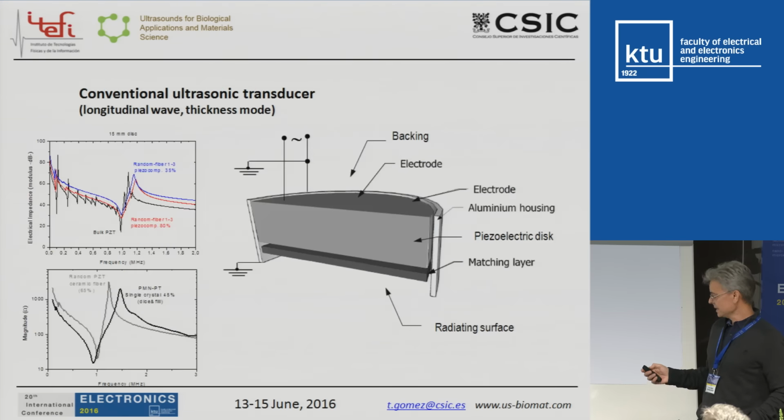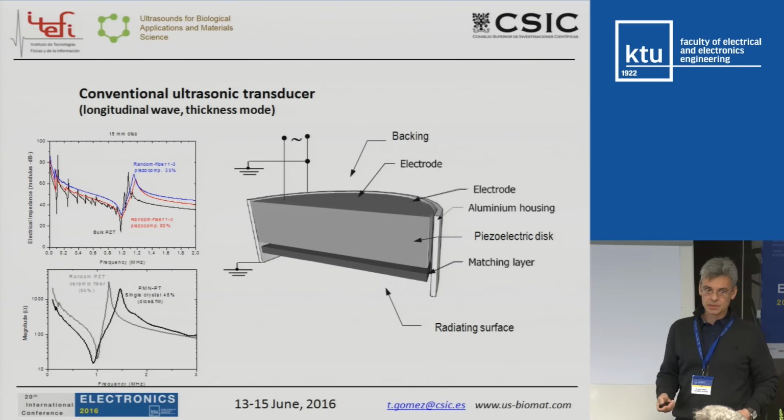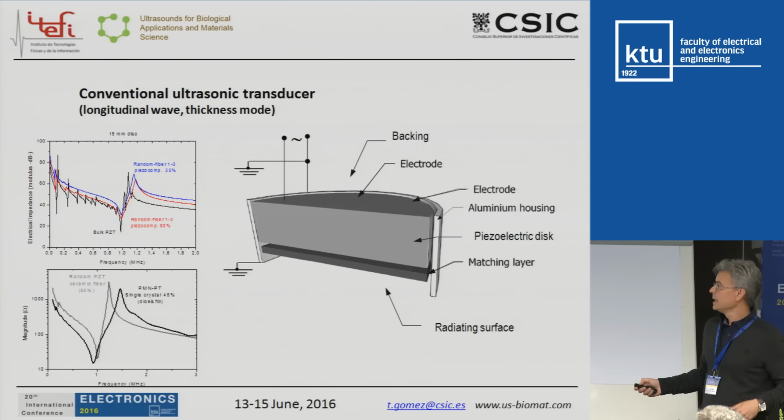But eventually we have a limit in the bandwidth, which is defined mainly by the piezoelectric element. This is the electrical impedance of this piezoelectric element, and the larger the separation between this peak and this peak, the larger the bandwidth, because the electromechanical coupling is larger. You can see that this here is the bulk ceramic, and the bandwidth is not very large.